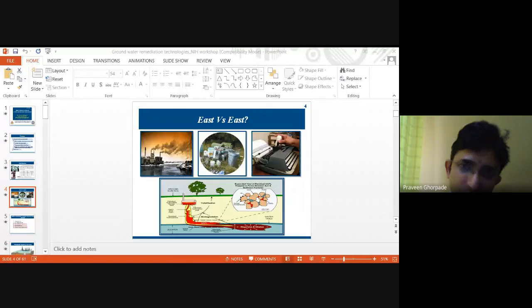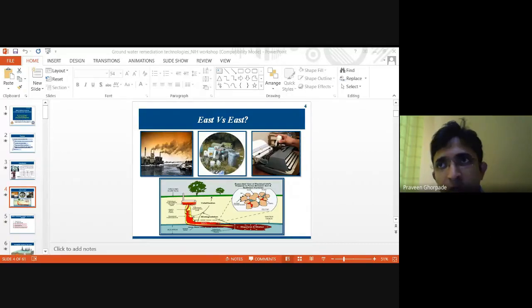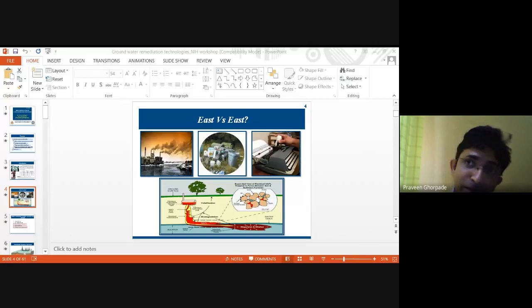Now, when you look into this type of problem of industrial waste, where industry is leaving its effluent into the water, we speak of ETPs, effluent treatment plants in industries, but it is always a questionable thing in India how well the ETPs are working. Or it could be as simple as some solvents used in paints, or solvents we regularly use, like typewriter correction ink, inks in our regular printers, or for that matter nail polish or nail polish removers. You have thousands of chemicals, and if they enter water, what is likely to happen? These are very different categories of chemicals which we have not concentrated on treating in India, especially in water treatment plants, wastewater treatment or effluent treatment plants. They really don't consider these types of pollutants.